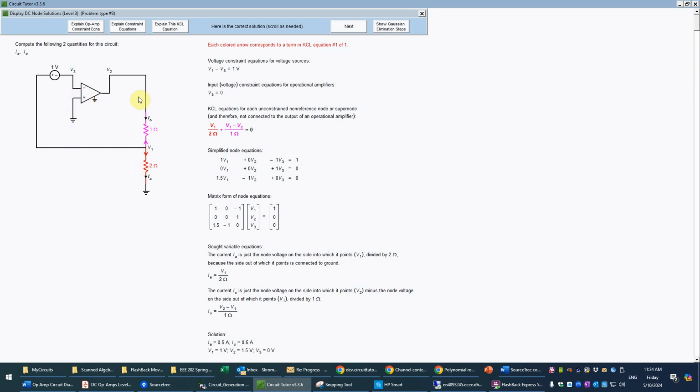And we also might ask, well, what is this circuit for? Its purpose really is to convert a voltage input to a current output. This is called a transadmittance. The gain is a current divided by a voltage, which has units of Siemens. And you see, whatever the voltage is here, basically that voltage divided by this resistance is going to be the output current. So by adjusting this resistance, we can make that current be pretty much what we want it to be. And so it's a convenient way of converting voltage to current, which is useful in some types of circuits. So this is a special purpose transadmittance amplifier.